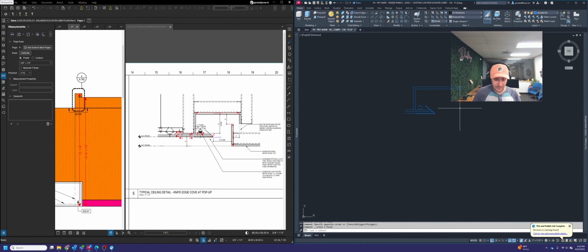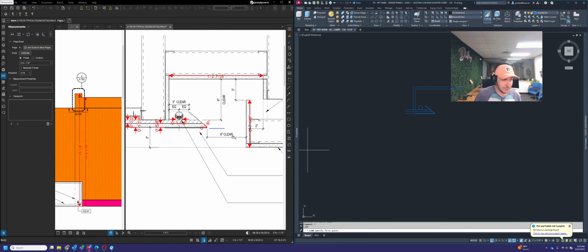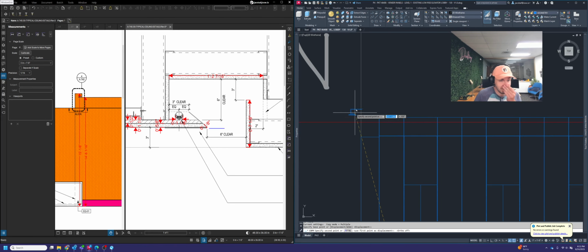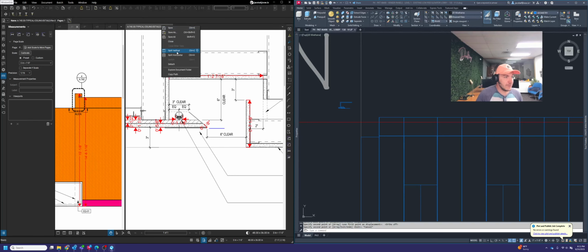And again, just to make sure, they're showing 6 inches clear here. So I think what I'm going to do is, probably shouldn't have deleted that so soon. I'm going to connect these dots here, just like that. Draw a line at 6 inches here to show what that would be. And then I can then accurately place this on the drawing where I need to put it. So right now what I'm going to do is kind of leave that in the details area, but I'm going to use the copy command and I'm going to make a copy of it up by my elevation views up here. Okay, and then let me unsplit this if I can.